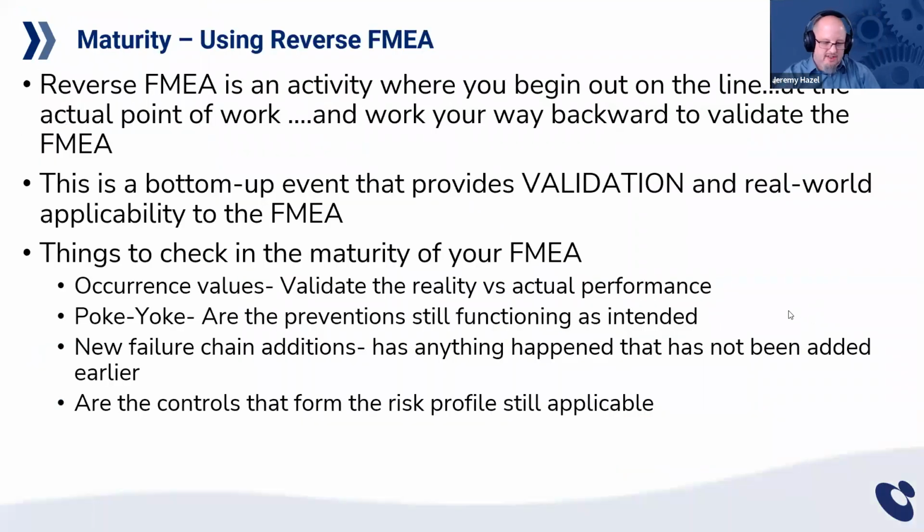Now, the first thing that I would really highly recommend you find a way to adopt. Now, as I say adopt, here's what some people heard: more work. I'm going to show you how to do this without more work, okay? Reverse FMEA is one of the tools we use here at Plexus during the maturity side. Now, the maturity side is the FMEA is out, PPAP's been approved, you're banging out 1 million parts for 5 years, it's mass production. And this only applies to PFMEA.